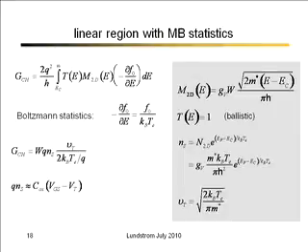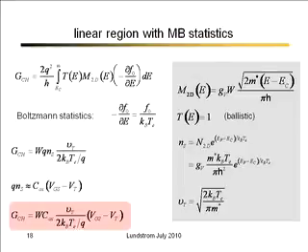I know that separately from MOS electrostatics. So that means we have a simple expression for the ballistic conductance of the transistor. And that's the bottom line here. That wasn't too difficult to derive. I want to discuss in a little bit, we'll try to make sense of that.